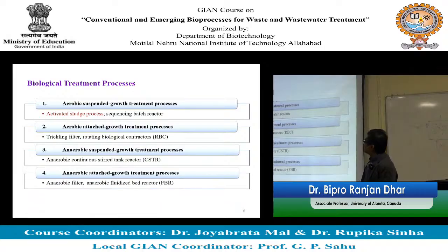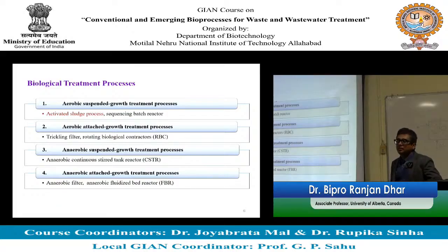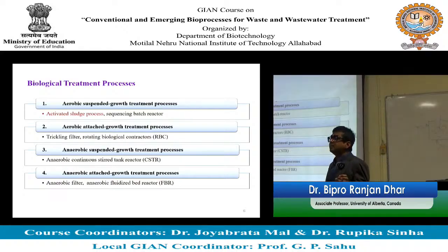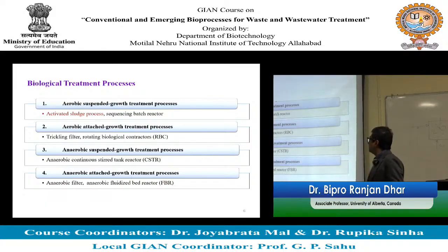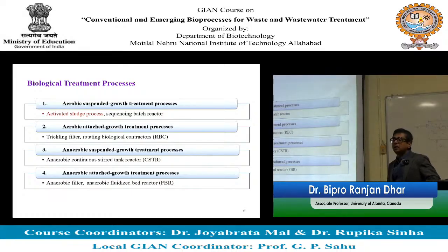For anaerobic processes, there could be an anaerobic filter, okay. So you could have a packed media, where wastewater can flow through the media. But one of the common challenges with running a filter type of system is that your wastewater should be free from any suspended solids. If you have any suspended solids, the filter media can be clogged, right. So that's a common challenge with running any kind of biofilter process.